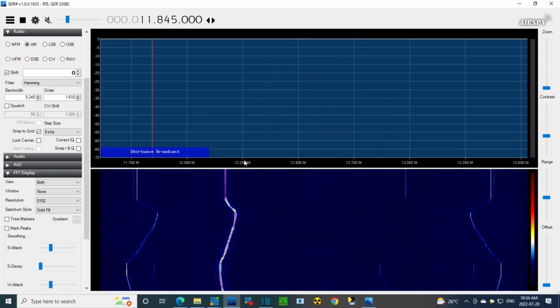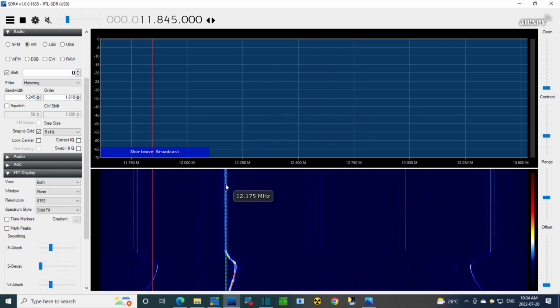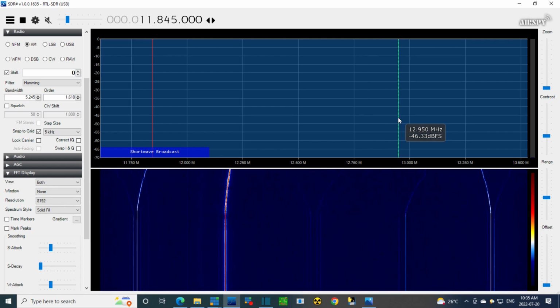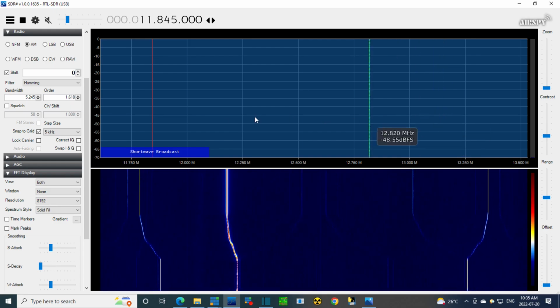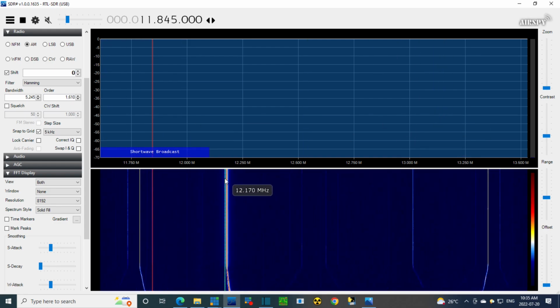If you look at these two lines, when I'm tuning the radio and they're moving around, you'll see that this one moves at twice the rate of this one. So for every 5 kilohertz I move this one, this one will move 10. Watch this again. It sure looks like that anyway. I really think that means this is the local oscillator. If this is the local oscillator, the radio is currently tuned to a frequency 455 kilohertz below that.